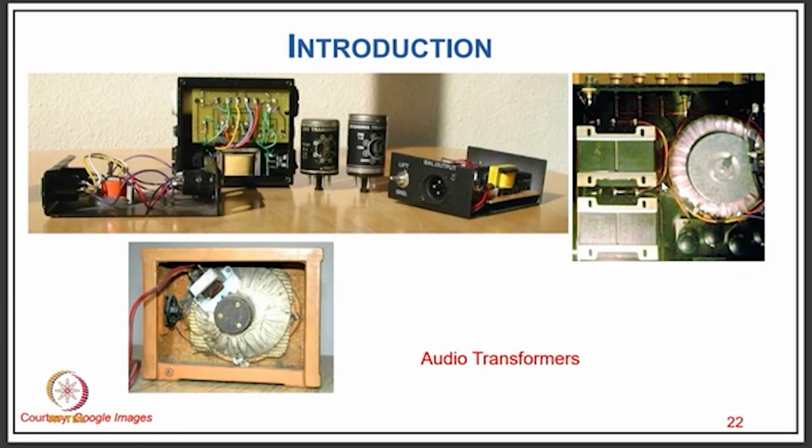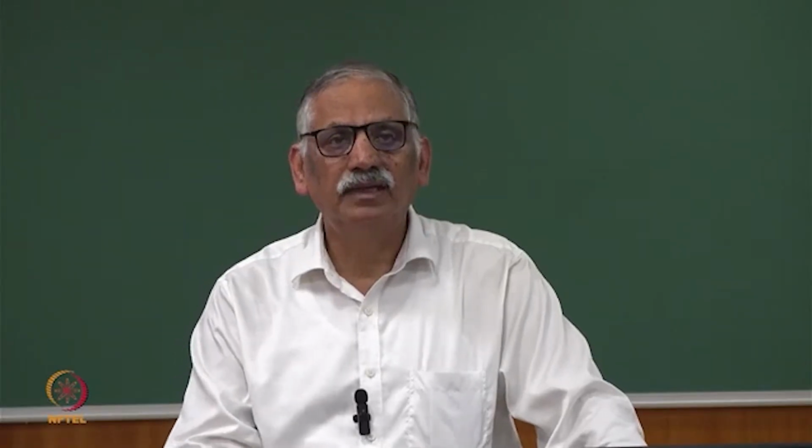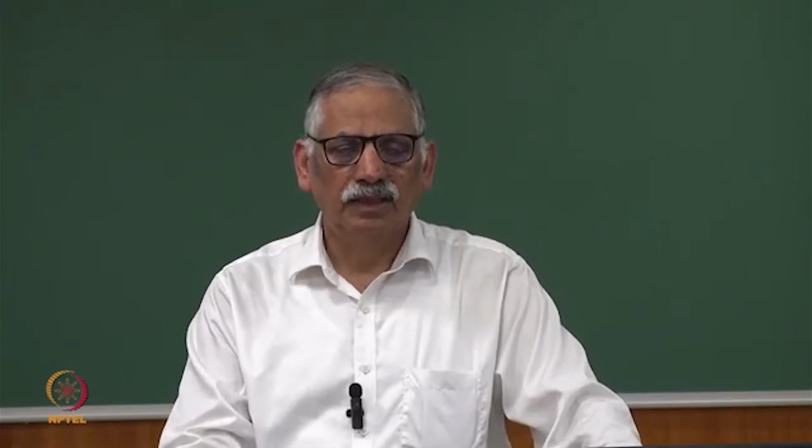Then you have different audio transformers which are used typically in your electronics, your amplifiers, sound amplifiers, a transformer which is normally used for audio frequency. This is the interesting application which you call impedance transfer using transformers. What we do here, we might have probably a mic or speaker of around 10 watt, hardly keeping about only 3 ohms, 5 to 10 ohms, which gets reflected as 5 to 10 kilo ohm on the amplifier. So that the amplifier is not loaded.